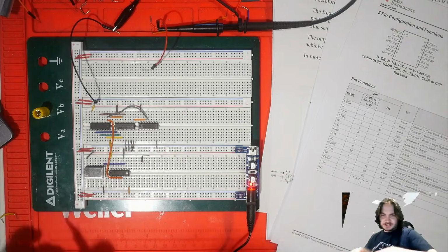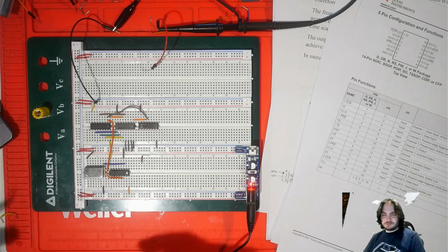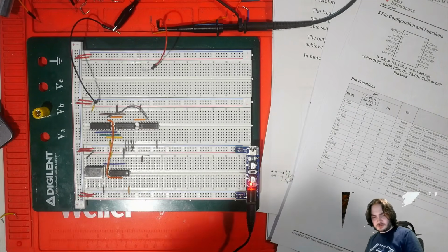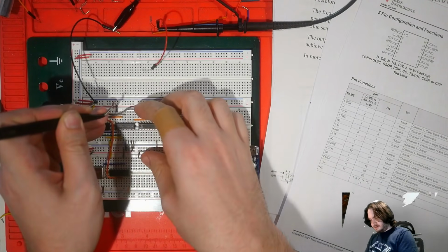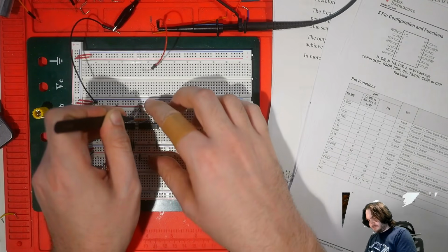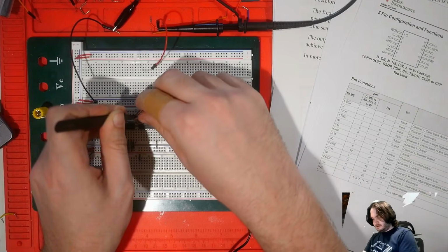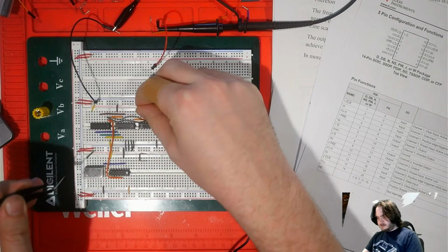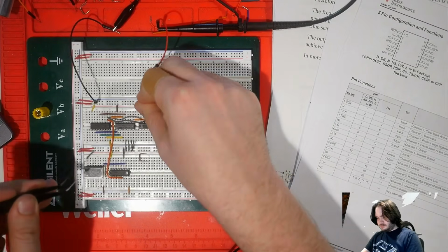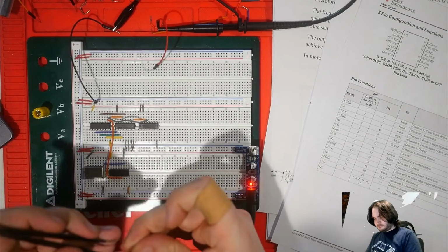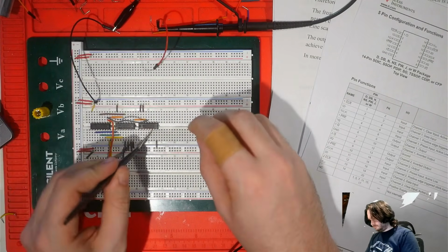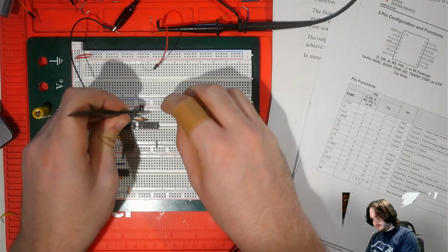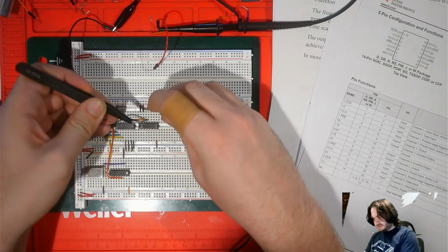Whenever one pulses, it sets the output to a certain value, and the other one sets it to the other value. Sort of toggle switch. But on this side of the chip, we're not using that. So we're going to tie those. Those are active low. We're going to tie them high. This one over here, so that they stay out of the way.